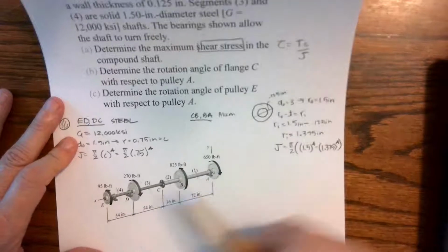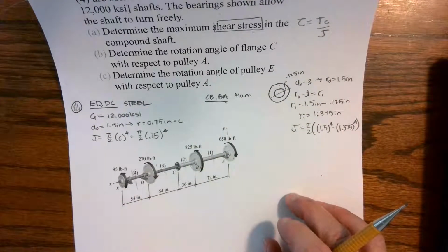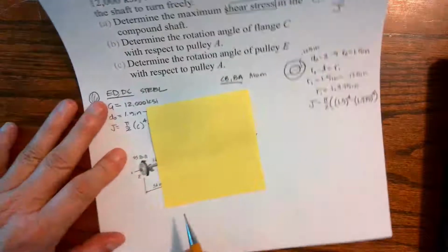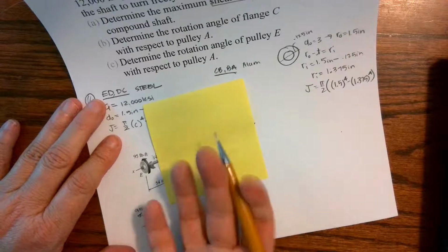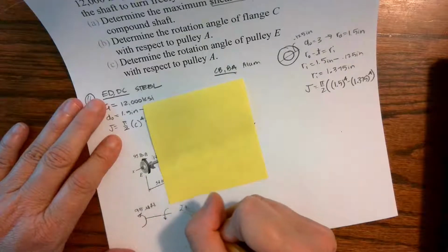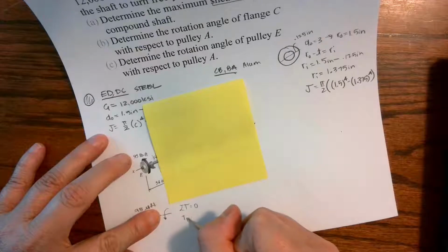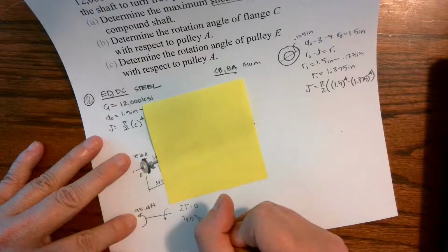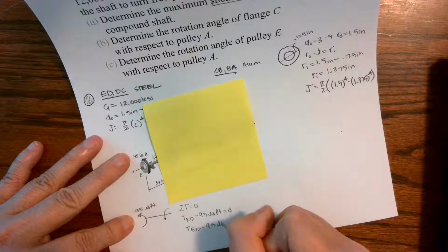So now I've got to find internal torques. That means I have to cut, and find my post-it note, because you all know I love my post-it notes. If I'm coming from the left to the right and I cut right here, I have this little tiny segment, and I'm twisting back at 95 pound-feet, and I'm going to assume internal positive, so that's twisting towards me. Now if I do the sum of my torques equals 0, I've got positive torque E to D, minus by the right hand rule, coming from right to left, minus 95 pound-feet equals 0. So my torque from E to D equals 95 pound-feet.